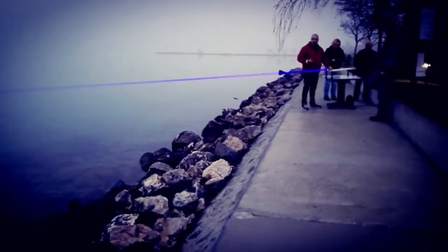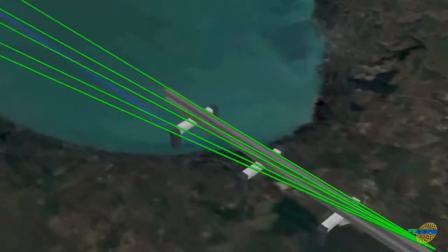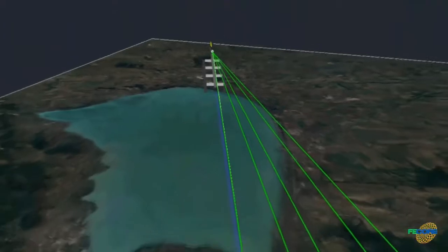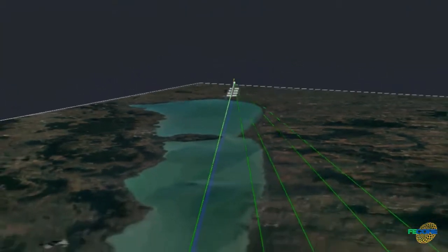The previous tests by Sandor had been conducted in the summer and showed some refraction anomalies. Therefore, it was decided to perform the measurements in winter conditions over a frozen lake to minimize the optical density differences along the path of the laser beam. According to the plan, the observation team would keep contact with the laser position as they walked across the ice while taking laser height measurements at the previously planned positions.